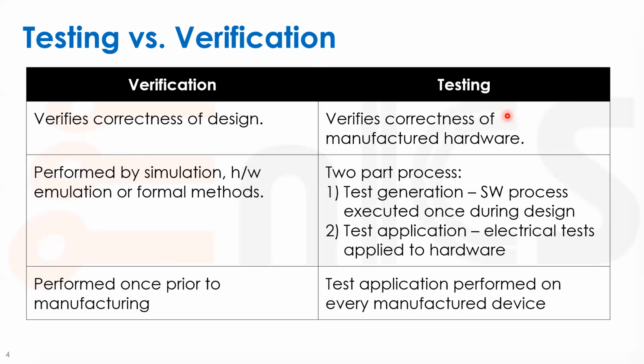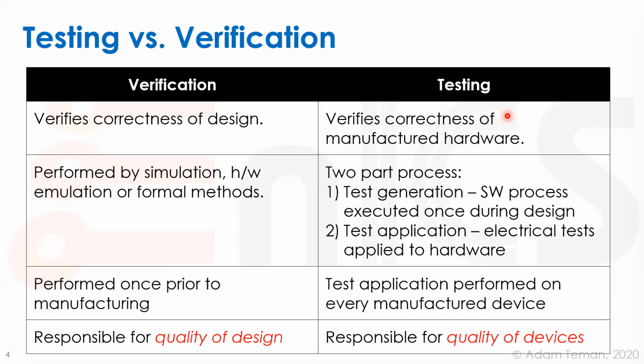Verification we do once prior to manufacturing versus test we do on every single device that we get. Okay, and the responsibility of verification is the quality of the design versus the responsibility of testing is the quality of the devices. Okay, so that's kind of a very rough difference between verification and testing.